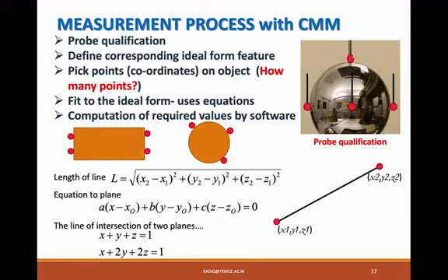You remember that when each point is touched, the center point of this sphere is taken by the system. So the system knows the information about the qualifying sphere, that is the dimensions, sphericity error, etc. Once it is touched, getting this coordinate point, the system already knows what the dimension is here. So this radius can be computed by the system. Similarly, this radius can be computed when the center point and the touch point on the sphere are known.